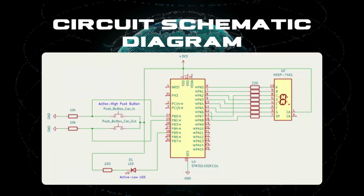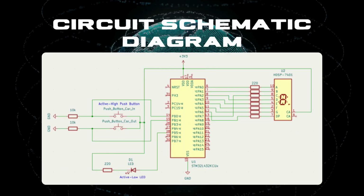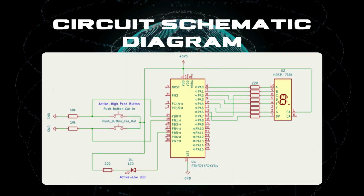This is our car park system connection. First and foremost, power connection: the STM32L432KC is powered by connecting the VDD pin to a 3.3 volt source and the VSS pin to common ground.